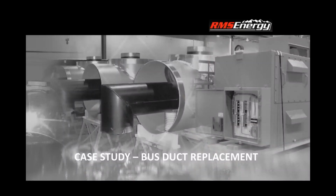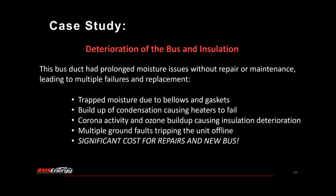And another case study here, this is a bus duct that was not maintained for extended periods of time. So it had prolonged issues with moisture and lack of repair and maintenance. Moisture became trapped in the bus duct due to improperly installed bellows and failing gaskets. The buildup of moisture and condensation within the bus duct led to failure of the heaters.